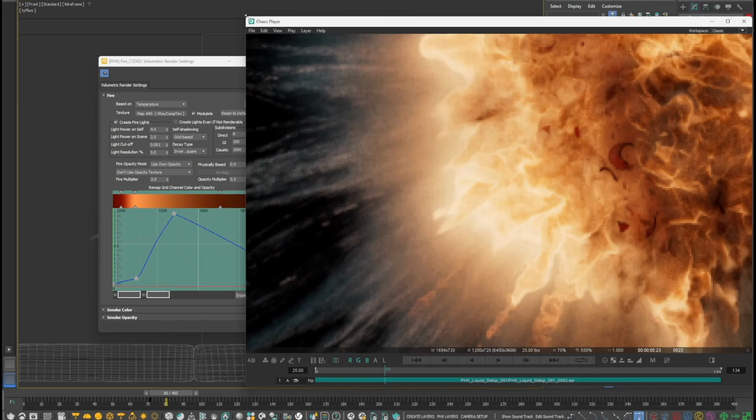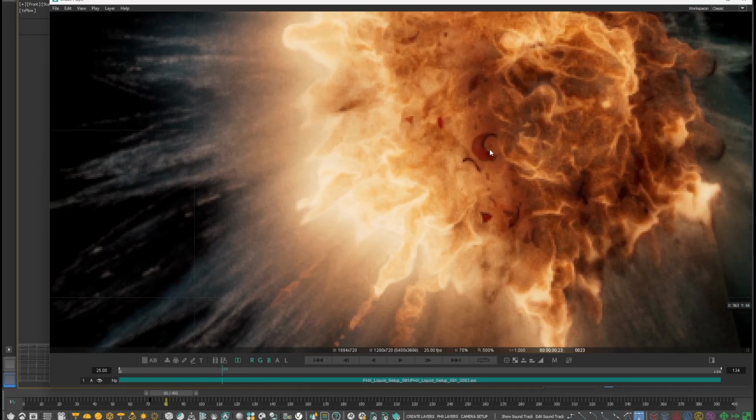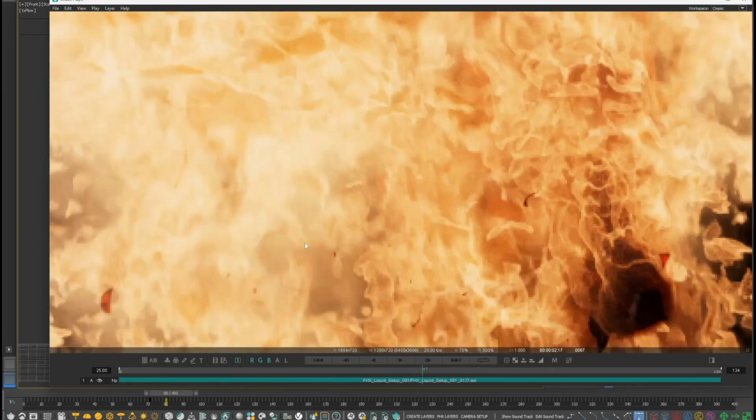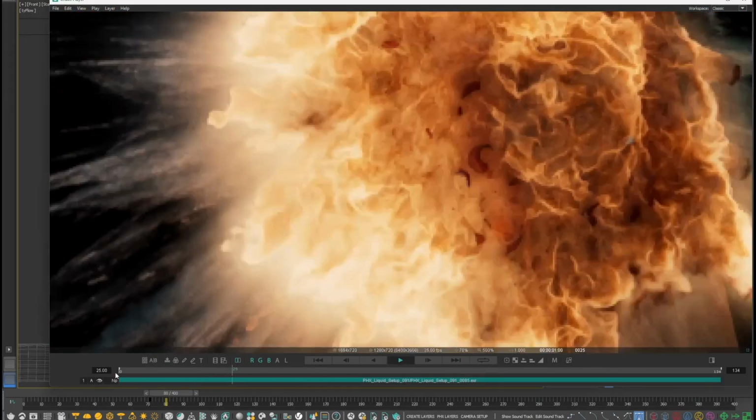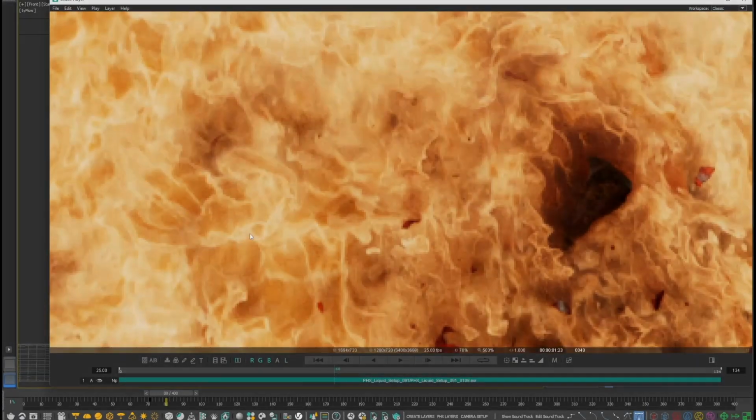I was able to ignite all of the fuel and get this rolling flames effect even without raising the energy and propagation speed values. If they were raised too much, the fuel would have expanded, making it look more like an explosion instead of having this creeping flames look.